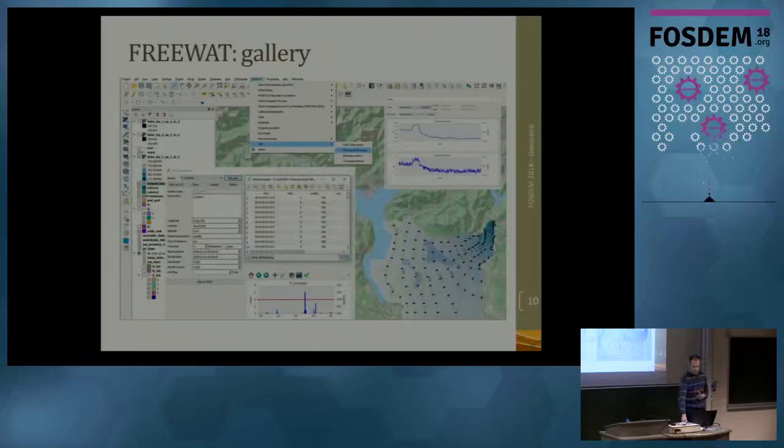This is for the observation analysis tool, where you have on the one hand options to gather data from sensors, insert them also in your database. That's this one. You can then easily export the data from the database to your MODFLOW model to use as observed heads, and then in the output you can get here what is the observed?